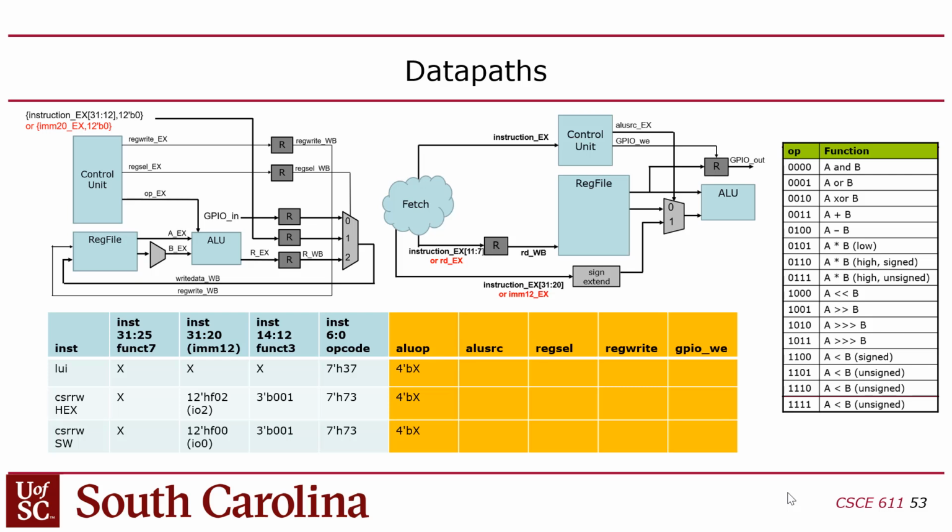So what do you set it to? You can set it to 0, or you can actually set it to X. If you set it to X, in Verilog, X is a don't care if it's in the context of an output, which is wildly confusing. In VHDL, it's a hyphen, and it makes more sense in VHDL. And you might say, what's the problem with X? Because X is used for conflict and don't knows, and it's used for other things, right? But it's also don't care.